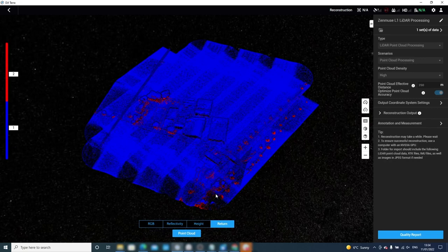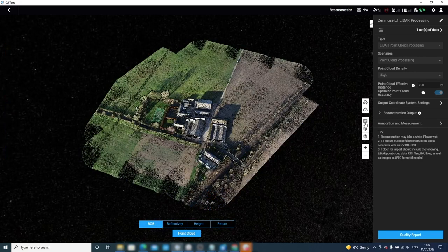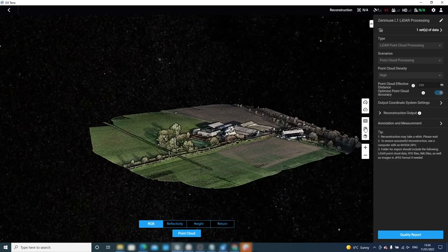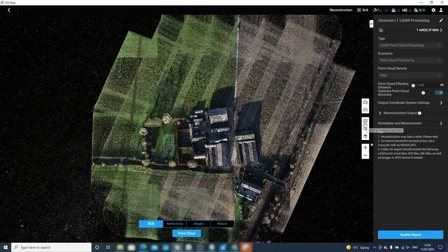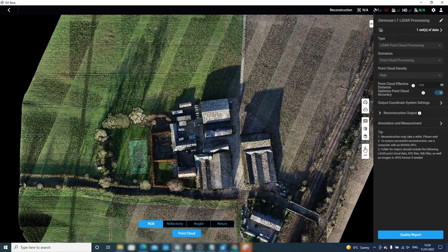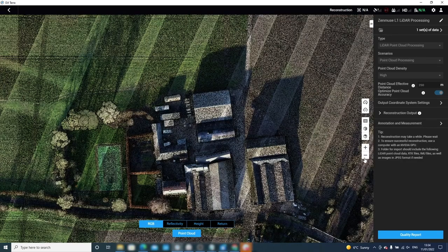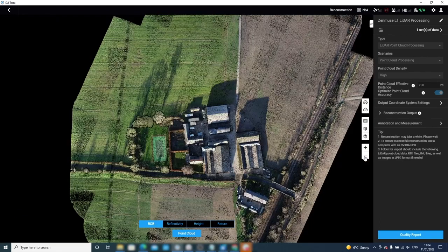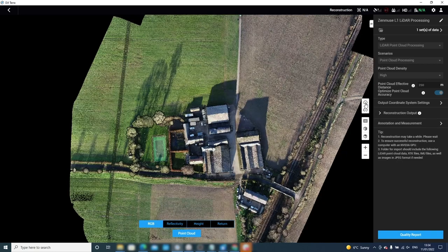There are also some basic zoom and navigation tools to use in DJI Terra. Firstly, you can zoom in and out of your point cloud using the tools shown on screen now. As for the view tools, the point cloud automatically displays as a 2D overhead view. If we want to return to 2D view, we can click the button that says 2D. Terra also provides a 3D point of view which can be selected by clicking the button below. In practice though, you will mainly use the mouse for navigating around your point cloud. The final view allows you to roam between 2D and 3D views and zoom right into the dataset. Navigation in this view will be explained more in the next session.